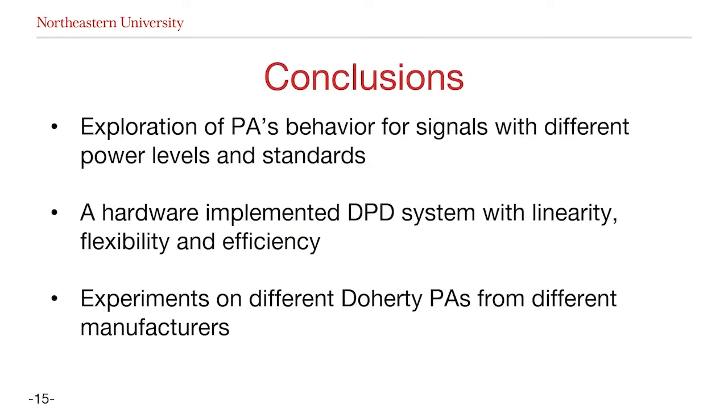And in conclusion, in this work, we explored the PA's behavior for signals with different power levels and standards. And after that, we implemented a hardware DPD system with linearity, flexibility, and efficiency. And in the end, our experiments are running on two separate and individual Doherty PAs from different manufacturers, which further proves our theory and our DPD systems.